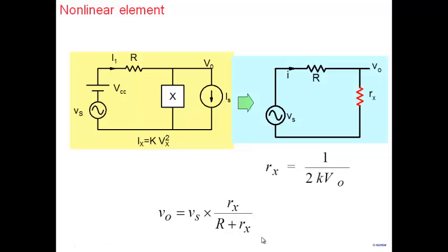So what is a small signal model? First of all, a small signal model is an incremental model of an element. Secondly, it's an incremental model of an element where I make the approximation that the changes across this are small in nature, and therefore we ignore all the nonlinearities that are there. We keep only the linear term. Now, you must be asking, how small is small? Is 1 millivolt small? Is 10 millivolts small?